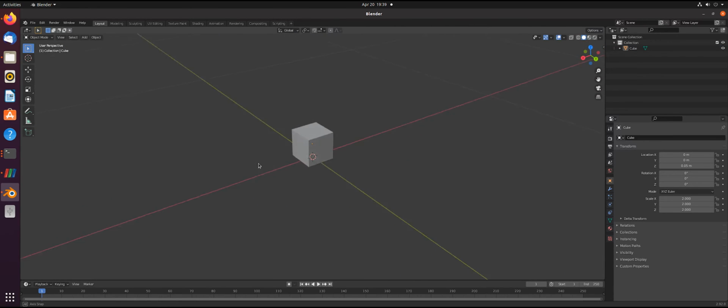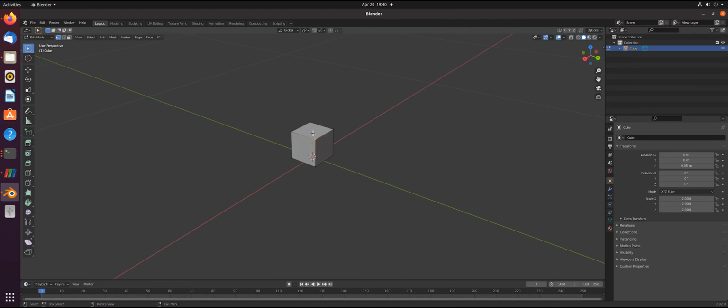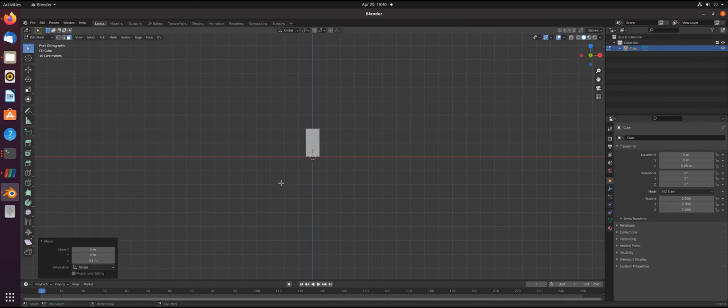This is possible by selecting the object and then pressing Tab to change into edit mode. I dragged the top surface 50 mm in Z direction. Therefore, I changed to face selection by pressing 3 on the keyboard, and then by clicking on the surface, I can move it with the key G. There are a lot of very good tutorials on Blender on YouTube, if you want to get more into this.